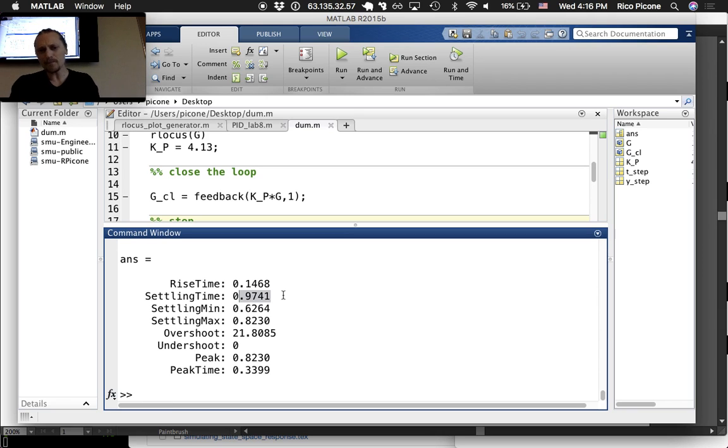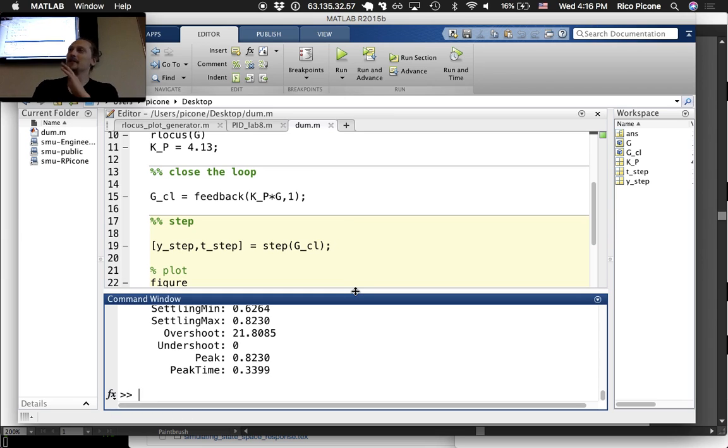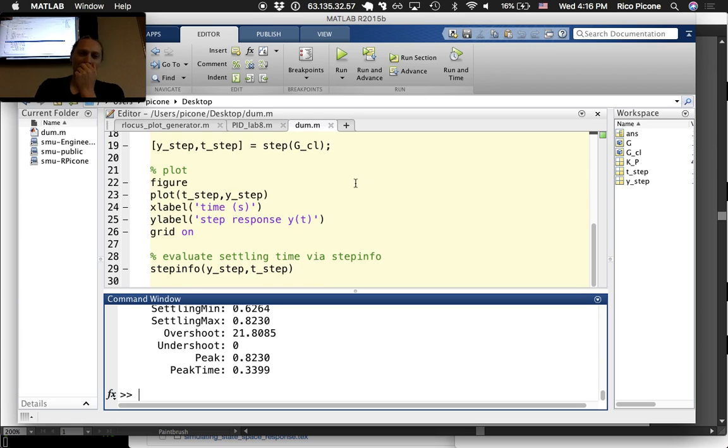Of course, there's a trade-off, right? The trade-off is that we probably had to flow more whatever our control effort is, current or whatever. So it's not like it's free. It costs, but when you're within 3% with your design, oftentimes you're like, that's pretty good. You could tweak it and get it more precise if you wanted. Okay, so we did it. We did a proportional controller that met that design spec.